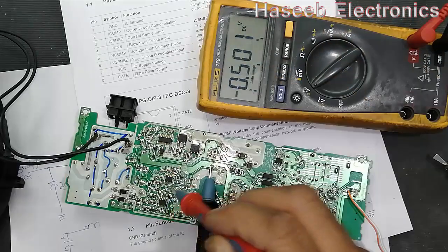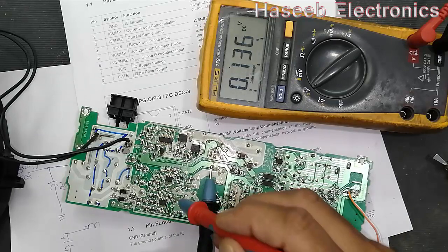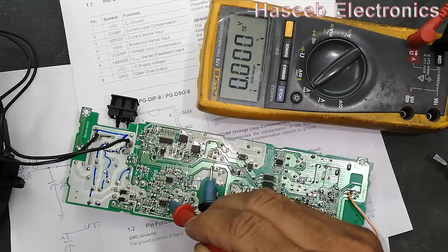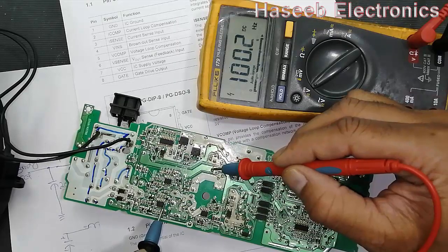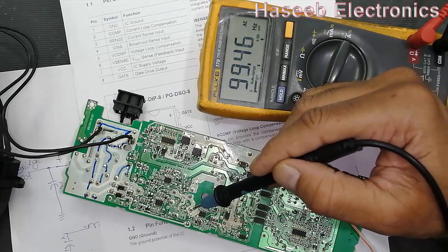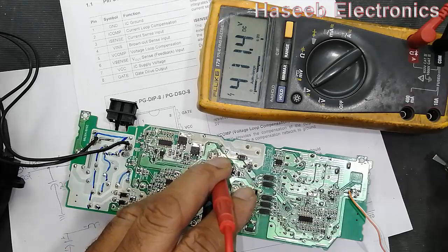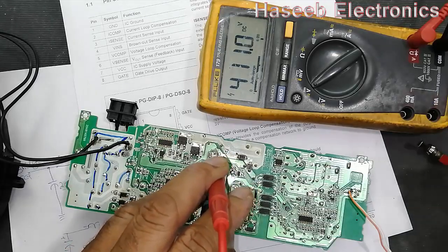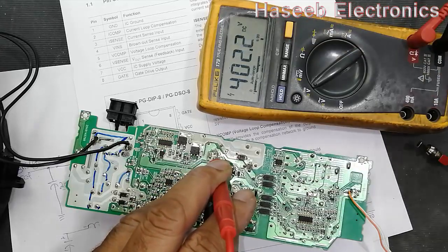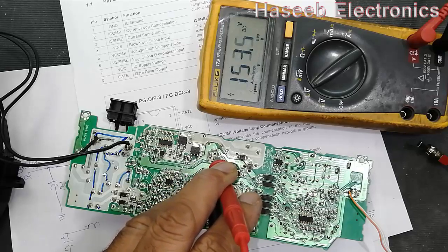Pin number 3, 0 volts. Pin number 2, that is I compensation, current compensation. It is 1.2 volts. Pin number 1 is 0 volts, that is ground. Drive is at pin number 8. So it is driving this gate, and it is switching this MOSFET, and we are taking voltage at the bulk capacitor. When I turn off this command, the PFC circuit will turn off and the voltage will be maintained at 330 volts.